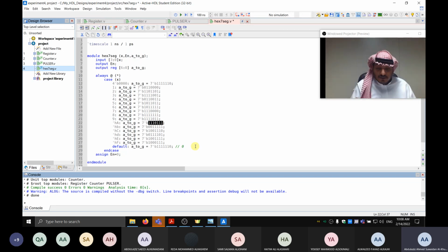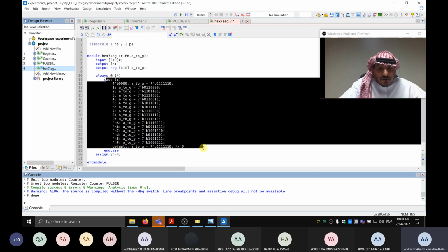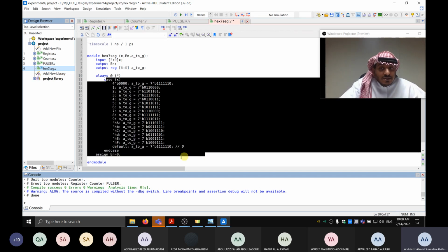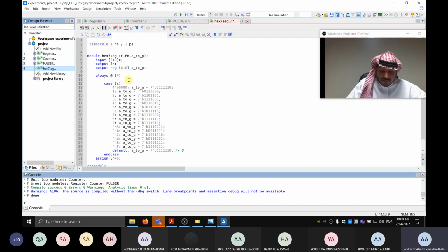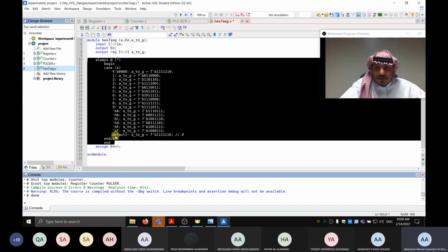Yes, Abdulaziz? Doctor, down we use enable as 0 and assign. Why did we use this? Yes, so now after you finish all of the cases and then you close the case, so what will happen? I said assign. Of course, I forgot to say begin. Like we said, begin and end. And then after the end case, there will be an end. Now I am outside of the always command. Now I said assign enable equals 0. You know, you have to send the enable either it's 0 or 1.